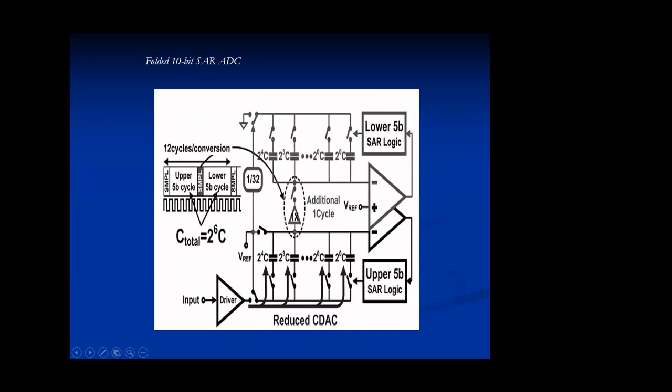And we have to use an A to D converter to convert this analog signal into digital signal. Normally in biomedical applications we will use more precision, because in biomedical, each and every bit value is important, because this is related to human health. In case of just image processing applications, not biomedical, we can use even a lesser number of bits, because their accuracy is not that important. But in biomedical applications, the accuracy is important, so we have to use more number of bits. So normally we will use successive approximation type A to D converter.